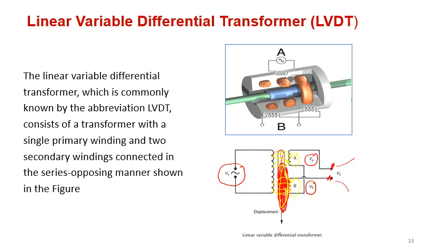So you will find more magnetic field coming to B, which means when I look at the output here, the output is not like before. The output between these 2 points will have a voltage, because the voltage VA is going to be smaller than VB, which means the output will give me a certain voltage. Now what caused this difference between A and B to happen? It is the displacement of the internal bar, this bar. I cover it in a different color this time. So when I take this bar down, I will find the voltage in B more than A.